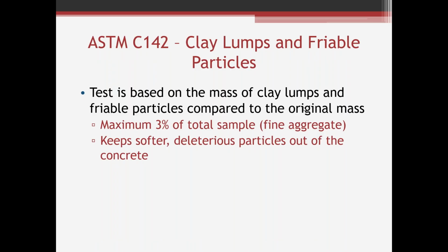Clay lumps and friable particles, also a pretty easy test. We're just looking for clay lumps, friable particles, those soft particles. We don't want those in our concrete because we want our concrete to be durable, right? Clay lumps are going to break down very easily. Friable particles are going to break down very easily. And typically we don't want our concrete breaking down because of the stuff that we made it with. So we want to keep all this stuff out of our concrete as much as possible. Although it does allow a certain percentage of clay lumps and friable particles, 3% by mass in your fine aggregate. Generally speaking, we don't want to see any of this stuff in there.